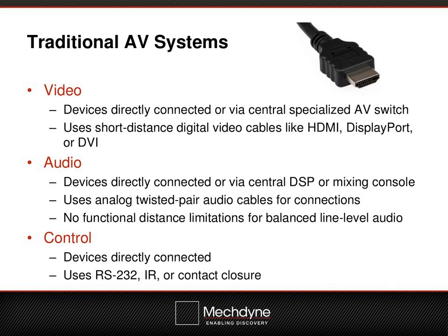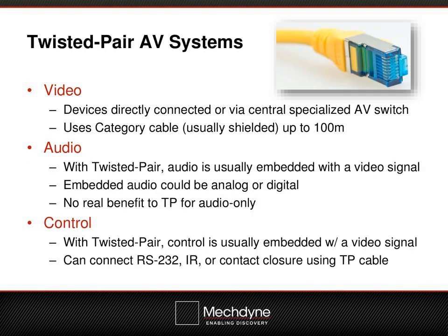And from a control perspective, these devices are directly connected to a control processor. In general, they're going to use RS-232, IR, or contact closure in a traditional sense. Now, I will say that on the control side, they've been network-based for a very long time, and so even traditional control for AV has been kind of outdated for a number of years now.